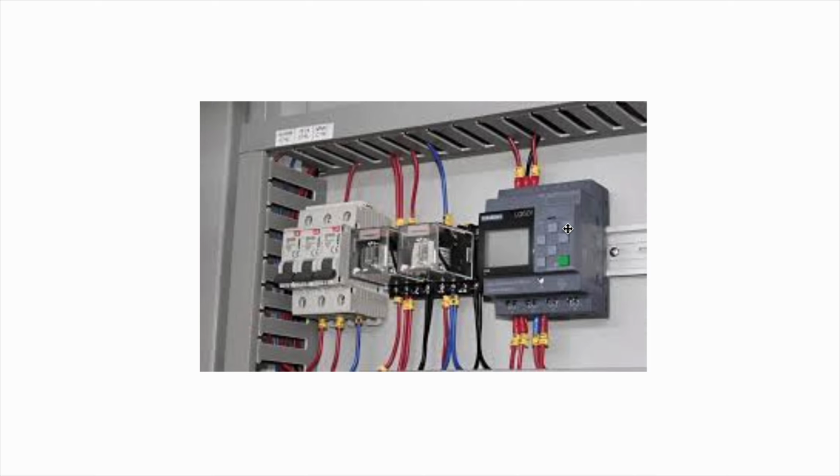So for a PLC, we have a processor inside. We have a memory unit. We have an input unit. We have an output unit. We have some indicators for some situations. We have some buttons for programming the PLC, and also there are some ports for connecting to the laptop and pushing the program logic to the PLC. And it also needs power. Most of the time it is 24 volts DC.